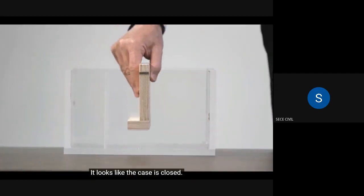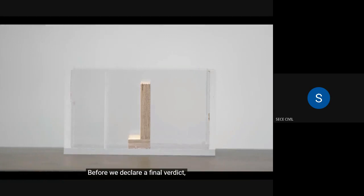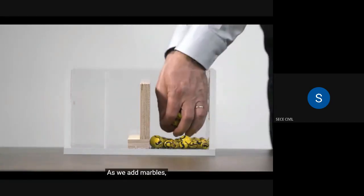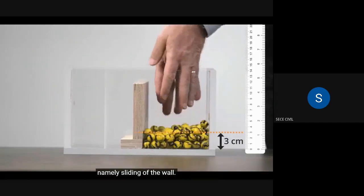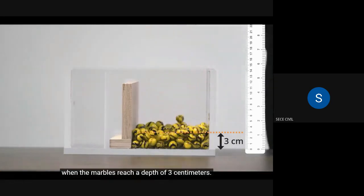It looks like the case is closed. Or is it? Before we declare a final verdict, let's use the model to find out what happens when the bottom leg points to the left, away from the marbles. As we add marbles, we discovered that the horizontal forces they produce create yet another mode of failure, namely sliding of the wall. And this occurs when the marbles reach a depth of 3 centimeters.